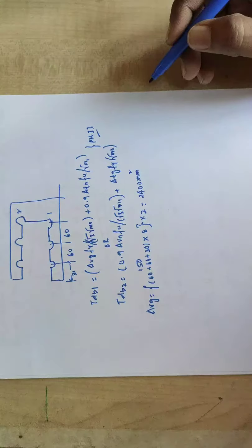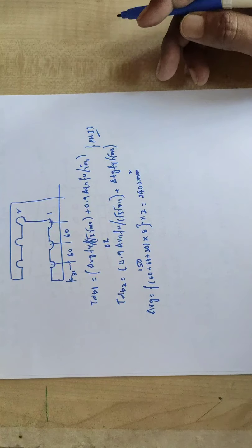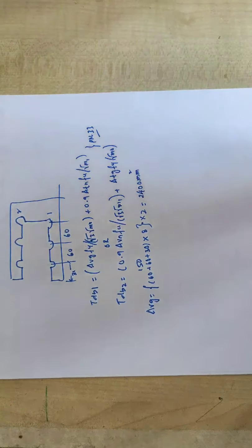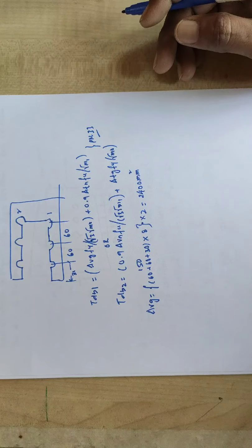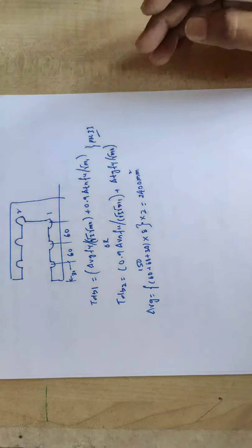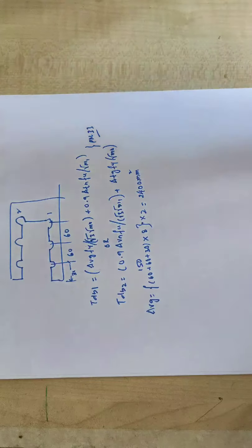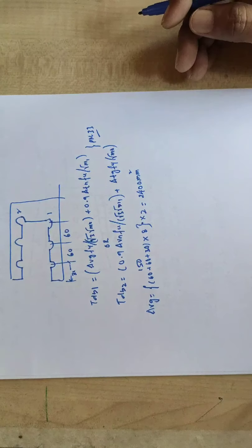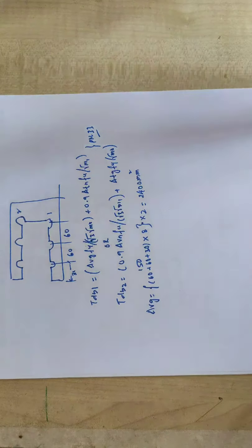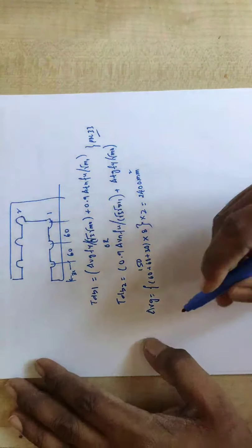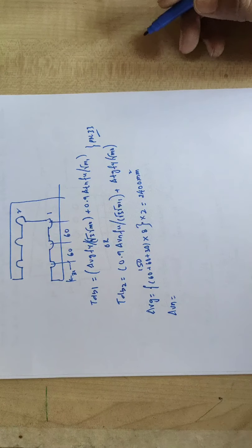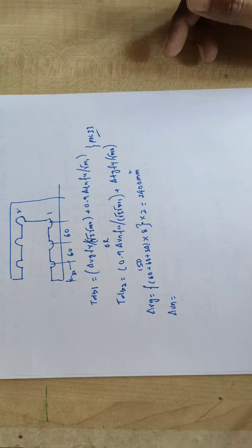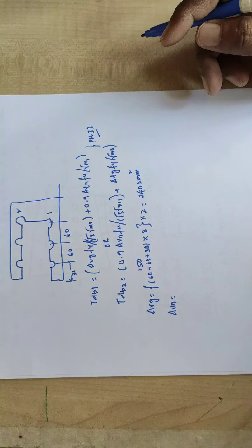What do we mean by Avg? Avg means we consider the whole area of block shear, where the block shear will occur, without deducting the holes. Avn means we consider the total area and then remove the bolt holes.